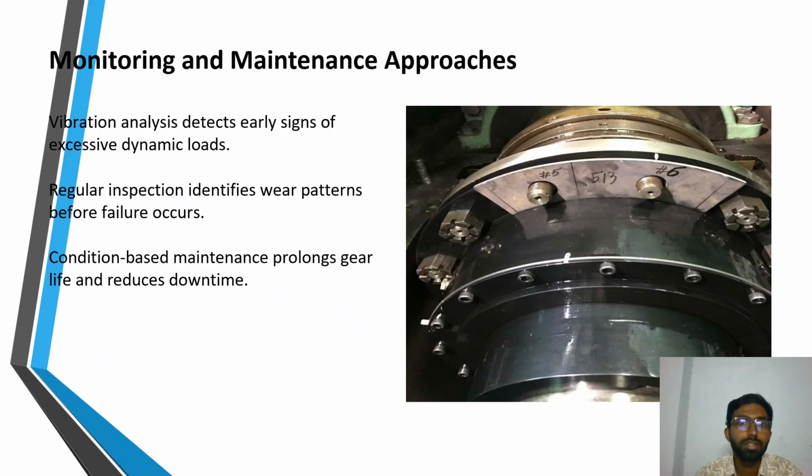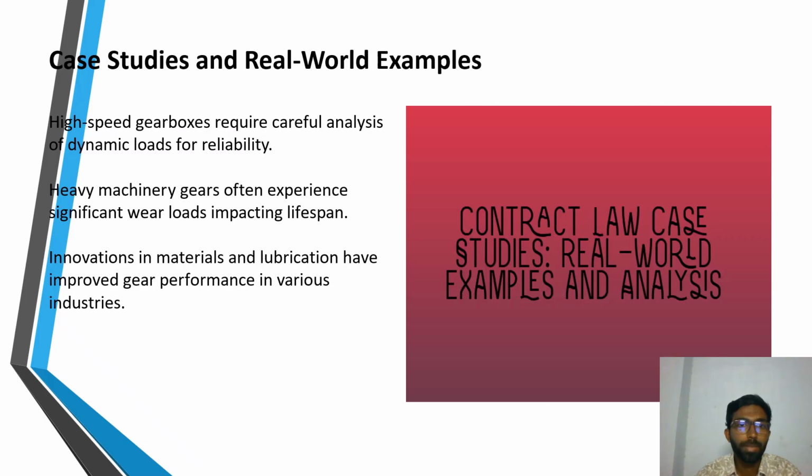Monitoring and maintenance approaches. Vibration analysis detects early signs of excessive dynamic loads. Regular inspection identifies wear patterns before failure occurs. Condition-based maintenance prolongs gear life and reduces downtime. Case studies and real-world examples.